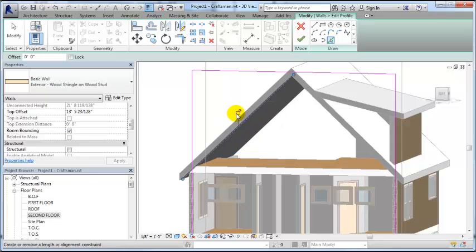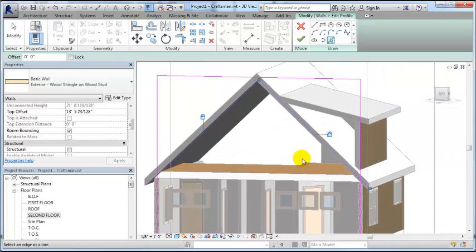Now I don't want that to move away from the rafter, so I'm going to lock that. I'm going to pick this same surface and do the same thing on this side. And then I'm going to pick this wall here, which should be aligned with the one down below. So that shouldn't be a problem. And I want this roof here, and I want that locked.